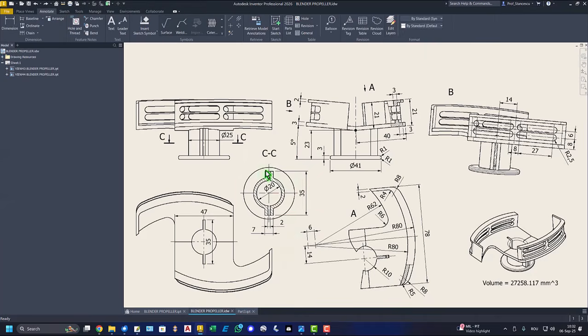Now we have to consider this view. We have to create a rectangle with 35 on 70 with join, then another rectangle of 35 with 2 as a cut from the part, then a hole of 20 in the middle.